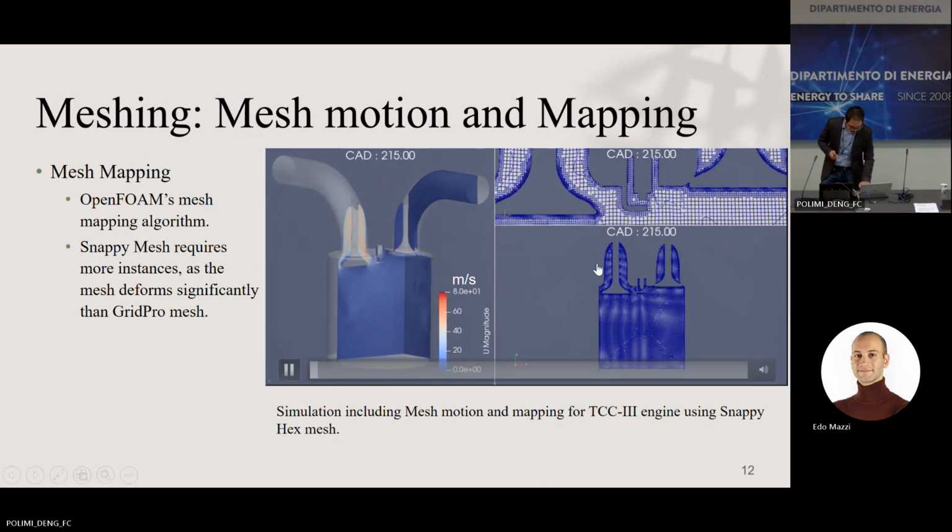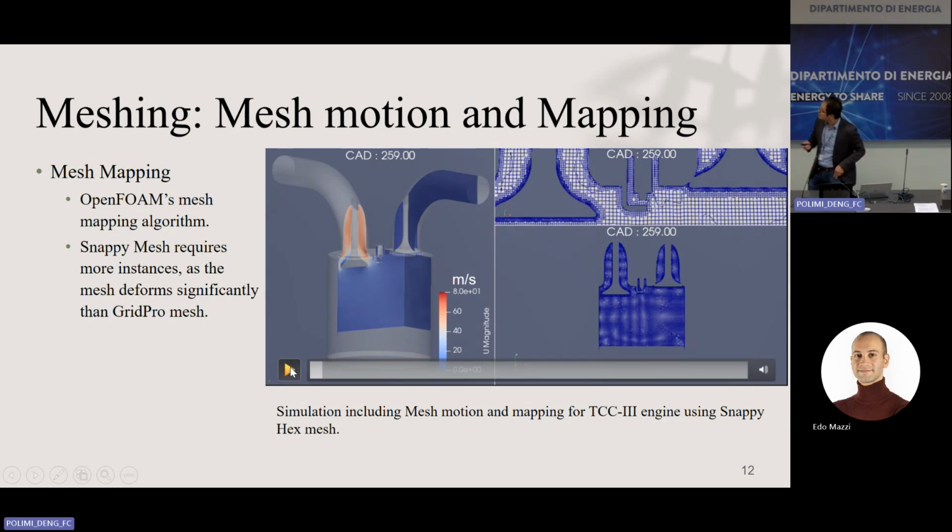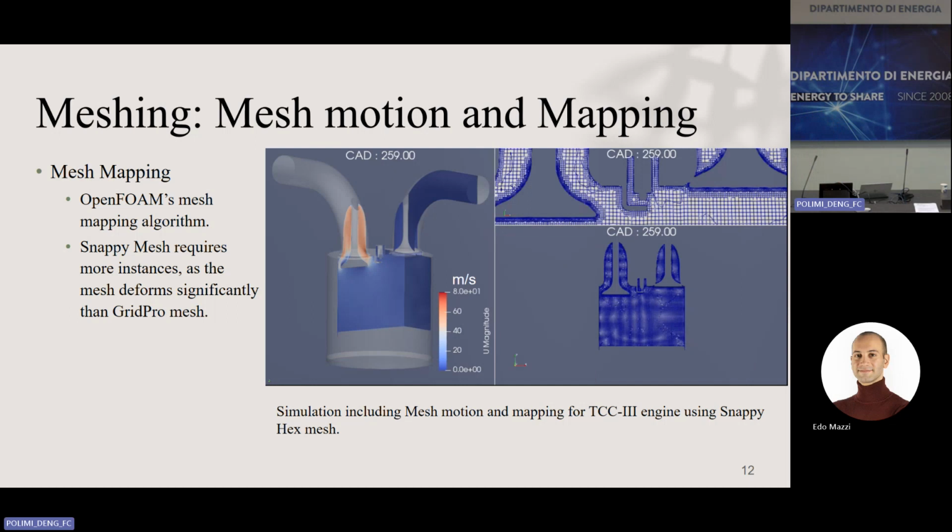Okay, and at this point, at the boundary, you have a cell which is half of the cell in the middle, the closest one. Okay, so with respect to the cell in the middle, how much is the boundary? Okay, so that's the point. This one would be 1 millimeter, and the closest size here would be refinement level 4. Okay. So compared to this refinement level 4, this should be half.